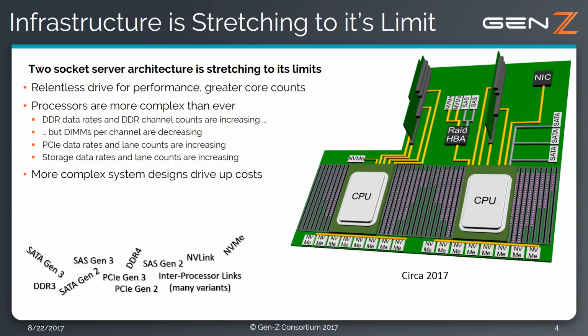Finally, circa 2017 to 2019, we will see CPUs that support 8 DDR channels per CPU socket and 64 or more PCI Express lanes per CPU. In this case, most of the PCI expansion is to support the requirements for greater numbers of NVMe SSD drives directly connected to the CPUs. In this time frame, PCI Gen 4 will emerge. All of this memory and I/O bandwidth is necessary to support the continuing rise in the CPU core counts.